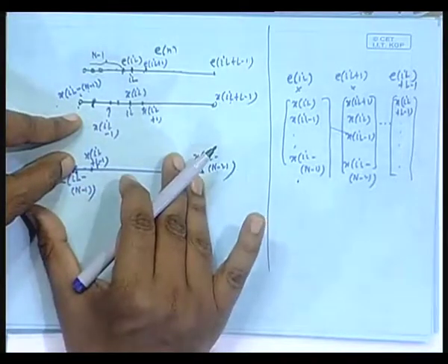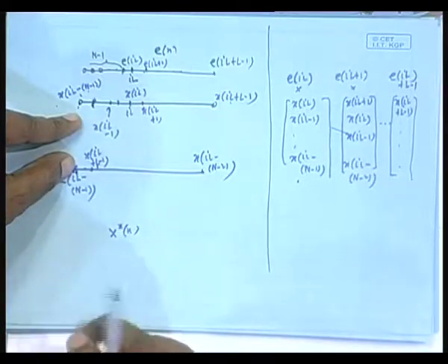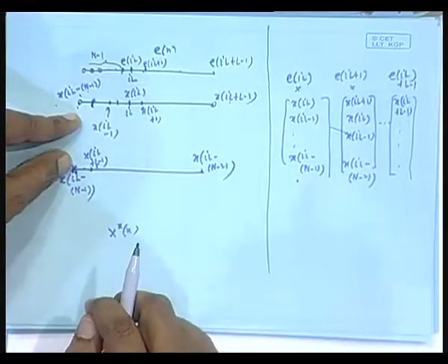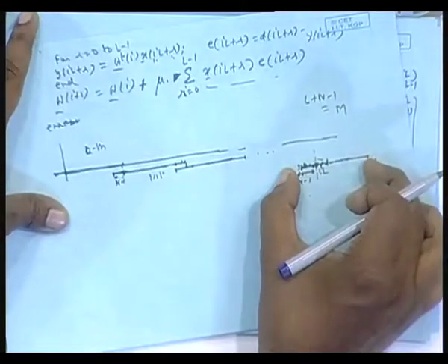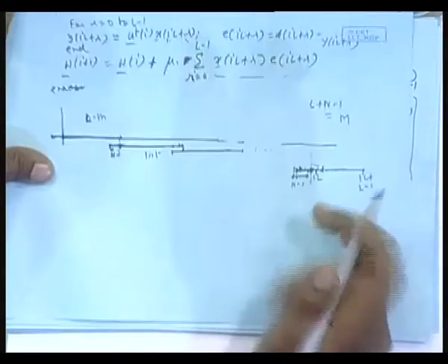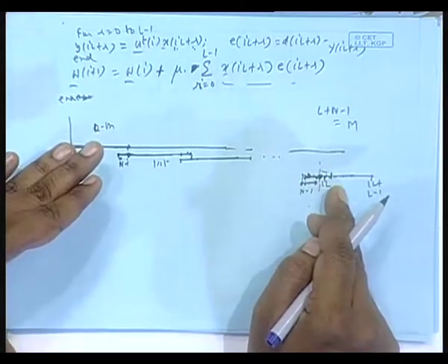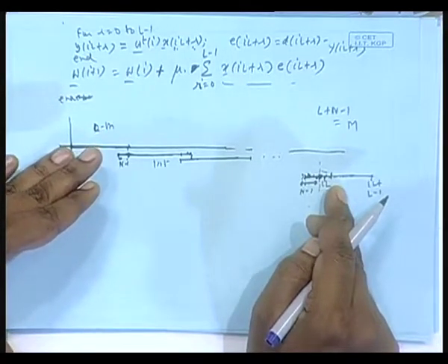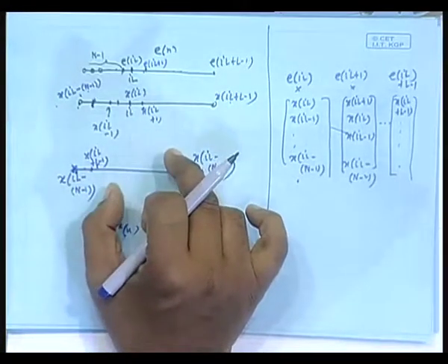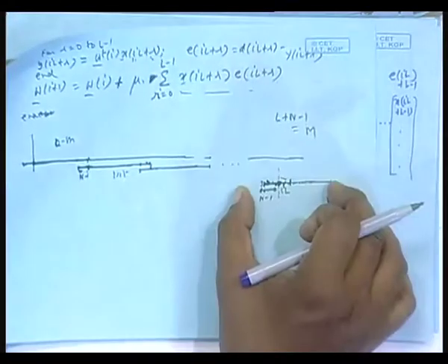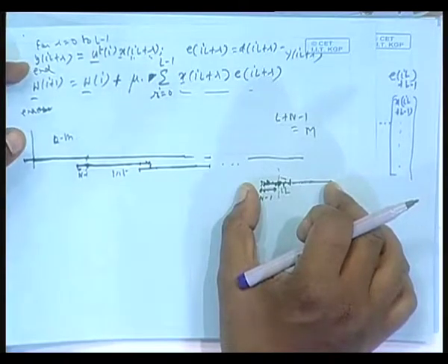Then if I take a DFT, I will get x star k, where x k is the DFT of what? This basic vector, simple block. Take a block, and where do I need this DFT? In the filtering part, the overlap and save method. Same DFT, I do not have to recompute the DFT of this reordered vector. I computed the DFT only once here. That is how I am saying the computational gains come. Otherwise, one more DFT would have been required, isn't it?